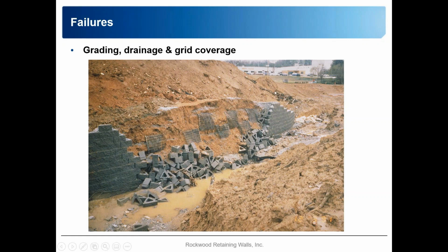Also, in this case, we have a massive amount of material that maybe the general contractor or the earthwork contractor hasn't addressed yet. They're probably going to move this off the site to someplace else. This is not a great area to store additional material because it creates a large capture area and helps divert a lot of water directly toward the wall.